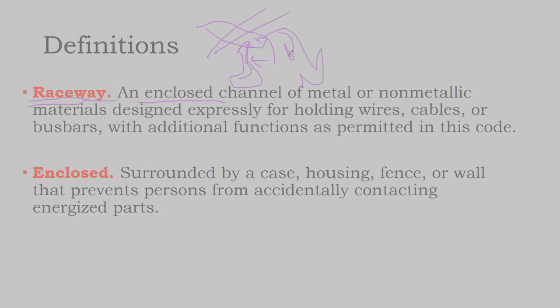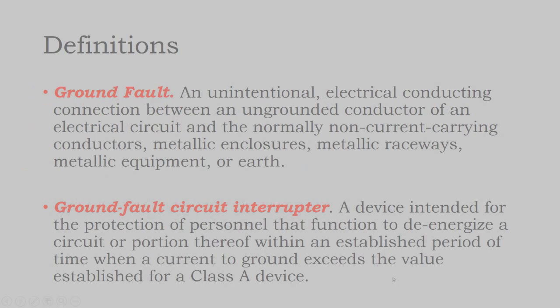And so you want to point this stuff out during the design process to the AHJ so that you can do your fancy building integrated solar projects, and not do them and then have a very authoritarian inspector show up and say, that's a DC conductor and it's not fully enclosed. That's a code violation.